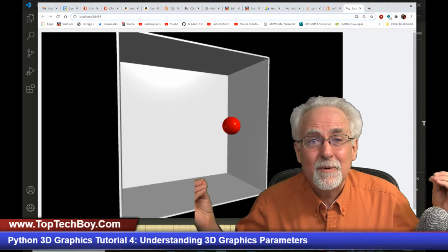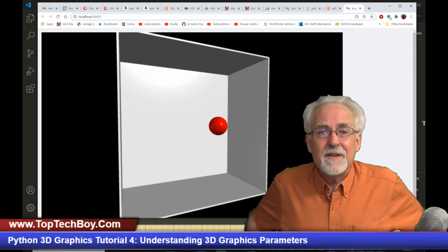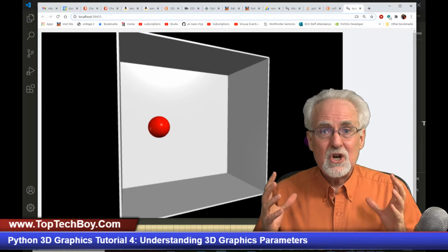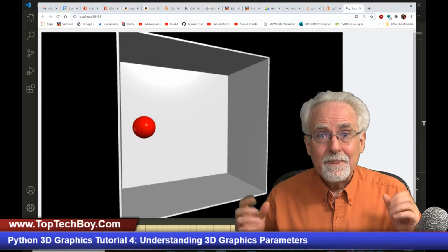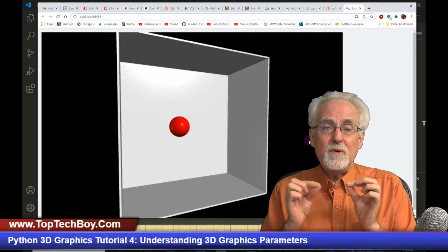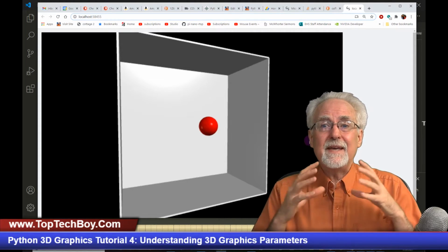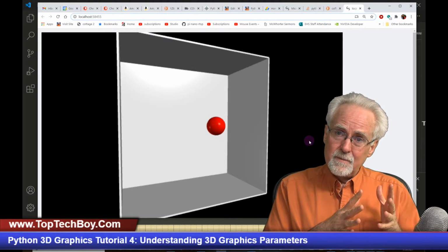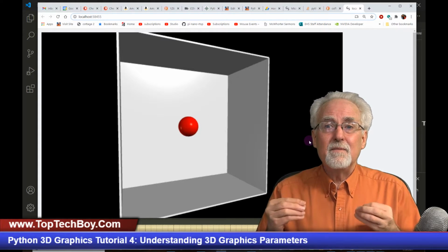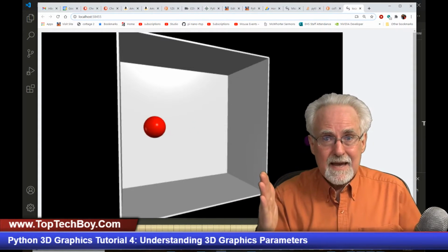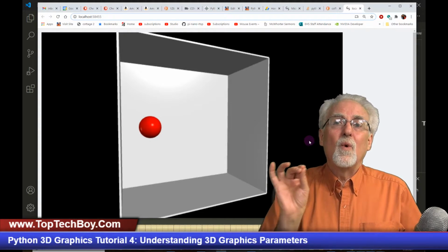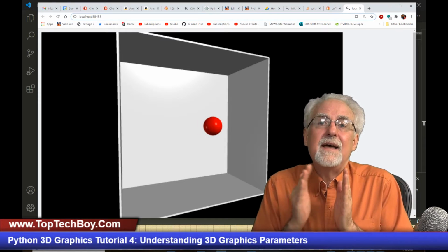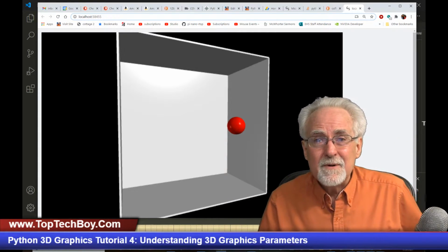I've shown you how to do parameterized models, and now everything's working. And this wasn't that hard. Number one, you start with a parameterized model. Number two, when you have quirky little things like the ball going into the wall, you make some new parameters based on those other parameters. You see, I didn't define a completely new parameter. I just made that edge of the marble reference to the center of the marble. So I haven't changed any dimensions. I've just added new positions within the parameter set that I had.